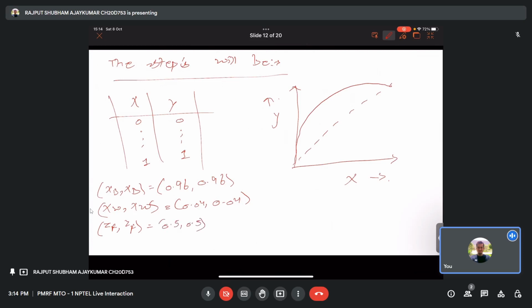So you have to look at all the points. Suppose xD is here, xW is here, and zF is here. You have to draw a number of ideal stages. You take a point here, go straight, come down, then again go straight, come down, again go straight, come down. Here I'm just drawing it randomly, but if you plot it on the graph, you have to determine the number of theoretical ideal stages required for the separation.